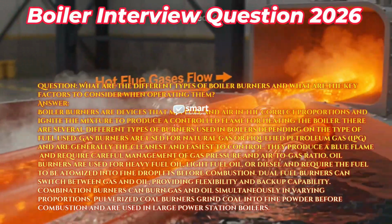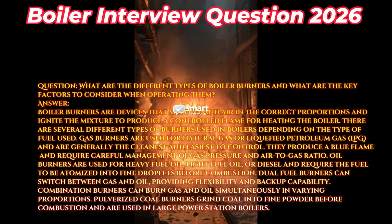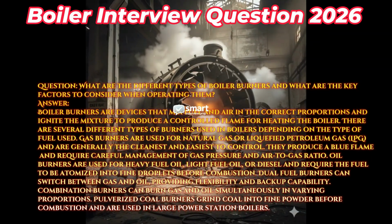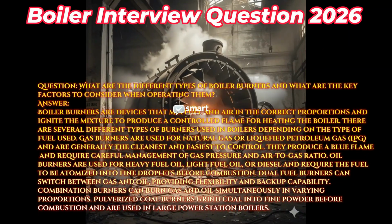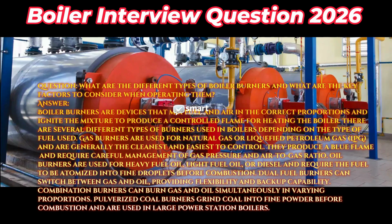Dual fuel burners can switch between gas and oil, providing flexibility and backup capability. Combination burners can burn gas and oil simultaneously in varying proportions. Pulverized coal burners grind coal into fine powder before combustion and are used in large power station boilers.